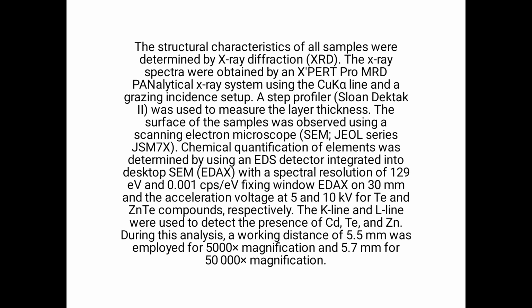Chemical quantification of elements was determined by using an EDS detector integrated into the SEM, with a spectral resolution of 129 eV and 0.001 CPS, fixing the EDAX window at 30 mm.